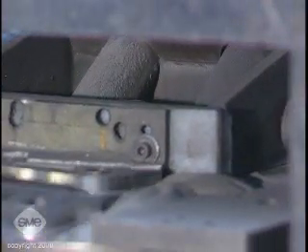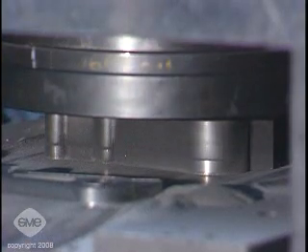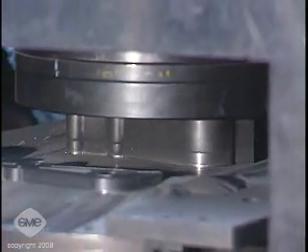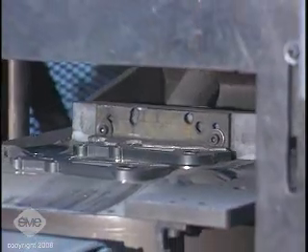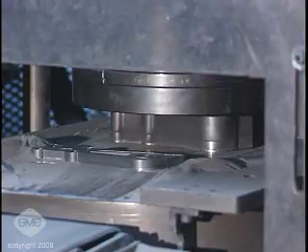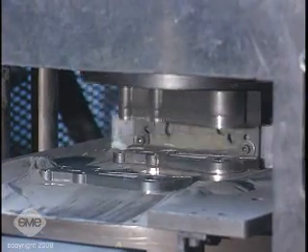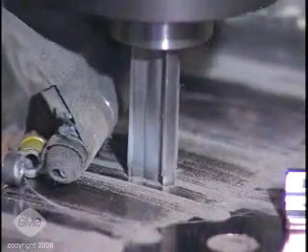In mechanical pressing, the powder is automatically gravity-fed into the die of a mechanical or hydraulic press and consolidated to a specific density. Pressures of 10 to 60 tons per square inch are created by the vertical action of an upper punch or by the double action of an upper and lower punch.